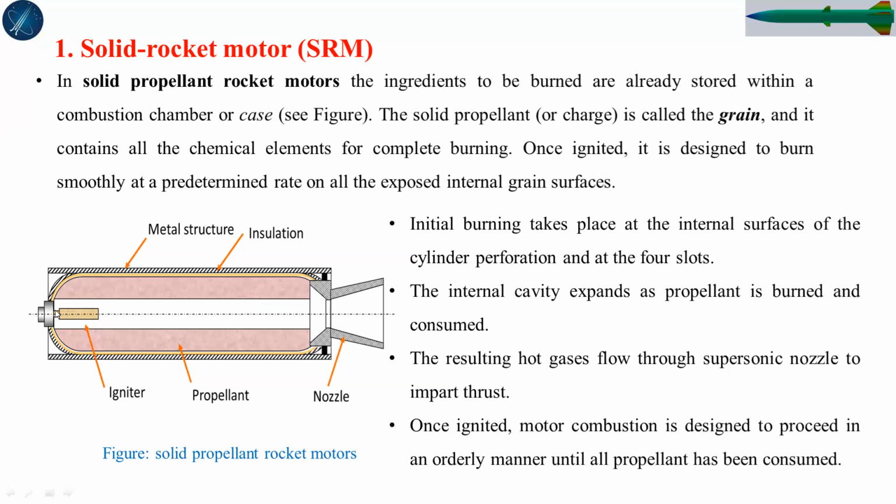Ignition system alone is a topic. Once a proper ignition occurs, ignition energy is released from the igniter, and this energy will transfer into the exposed surface of the solid propellant. This exposed surface is immediately caught by fire or high energy, and then it starts to burn internally. Once ignited, it is designed to burn smoothly at a predetermined rate.